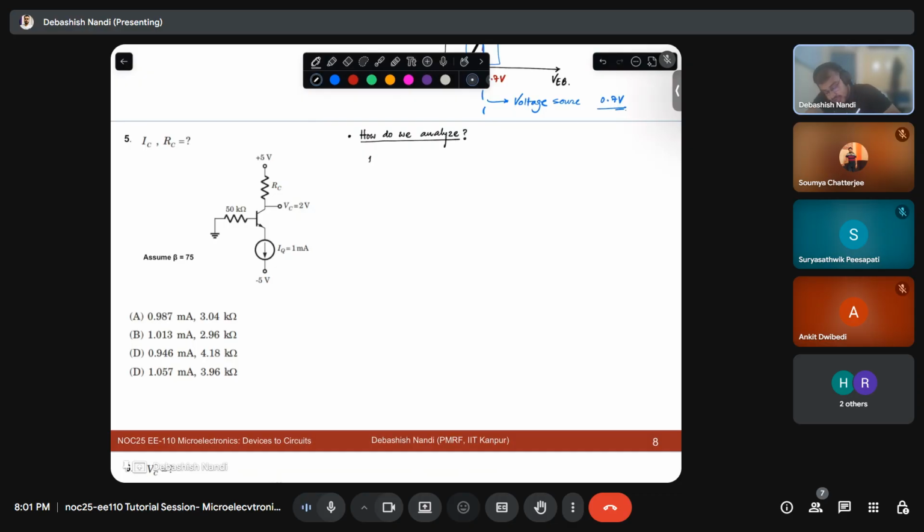There are two ways basically. One is to write the full nonlinear equations of I and V and use KCL, KVL and something we call the NR method, or Newton-Raphson method, that is used to solve nonlinear equations.